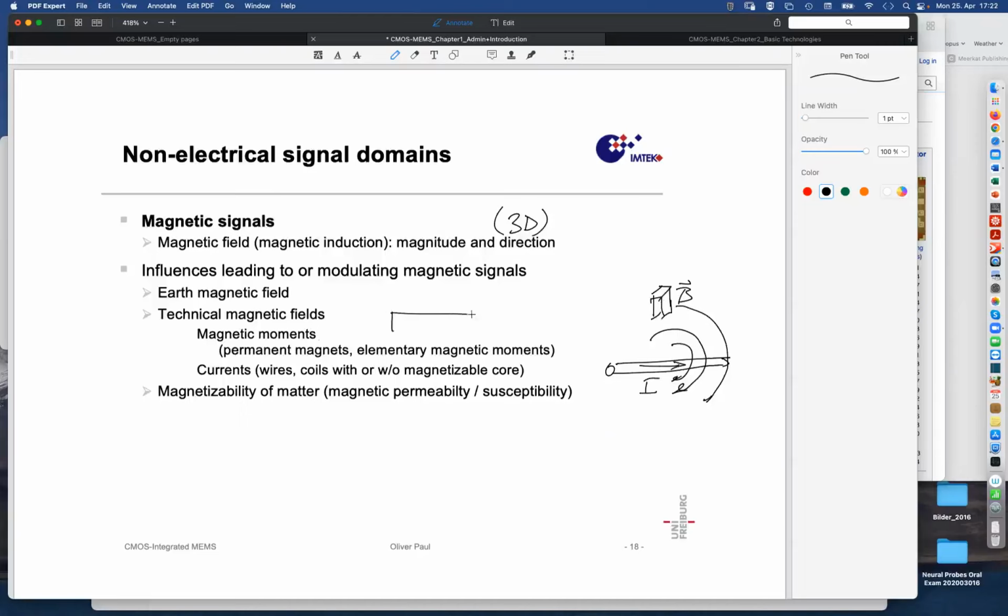But also you could have, of course, magnets with some north and south pole. I drew here a schematic thing. If this is mounted on an axle, it can move up and down like a seesaw. For instance, in a switch, cluck, cluck, the two positions of a switch. Imagine that you have a little magnet in there. If you move it from one position to the other, the magnetic field pervading space will also rotate with the little magnet. And now you have beside it a magnetic field sensor that senses that changing magnetic field.